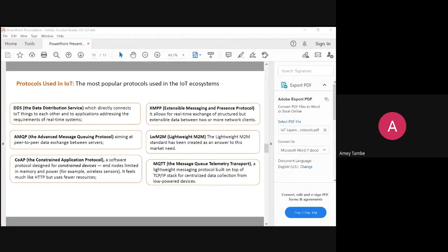And if you have QoS 2 enabled on it, then it is most reliable, but it is most bandwidth consuming. So though MQTT is completely designed for low powered equipment and low powered communication, in that also some kind of energy is getting lost. So if you set your MQTT communication to QoS 2, then it will consume more bandwidth, not more power, it consumes more bandwidth. And because the bandwidth consumption is more, the device on which MQTT is configured, and that device's antenna, is taking up more power. So that is the case.